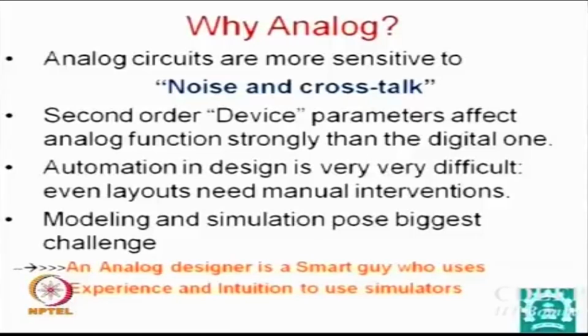That is called crosstalk. The worst crosstalk occurs if the signals are moving in opposite directions. If they are in the same direction, there is lesser crosstalk. If they are in opposite directions, it is x minus (minus y), so an x plus y kind of situation. So crosstalk is a major worry in most circuits now, digital included, or rather digital is worse right now, because you are putting too much interconnect there, too many lines going on, particularly in something like a DSP, which has less circuit, more interconnects. So in such circuits you will find the problems are only the crosstalks.